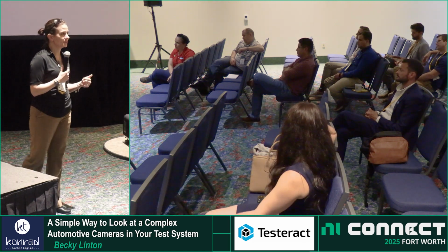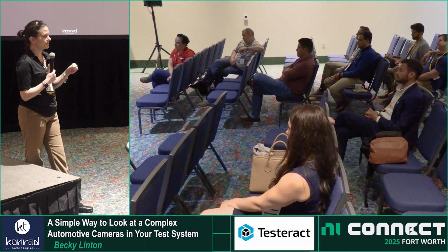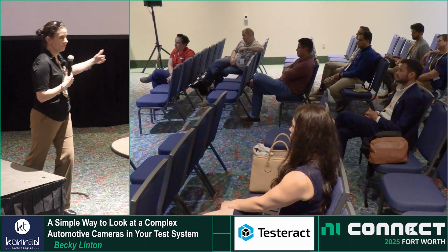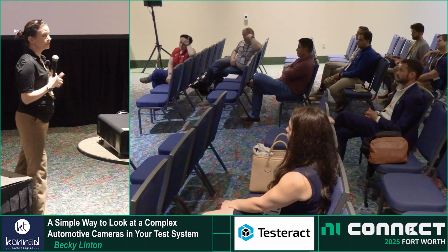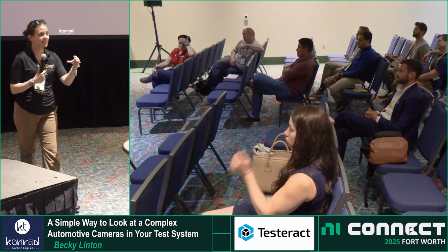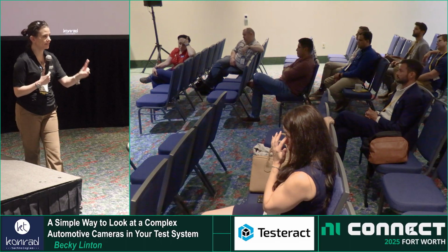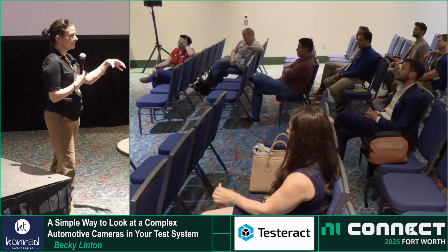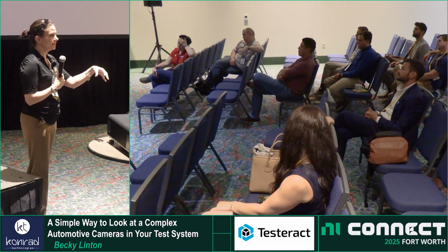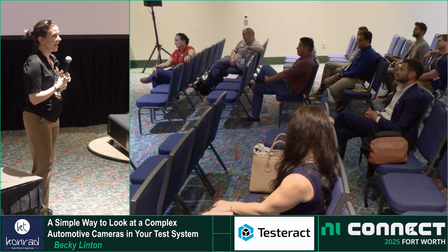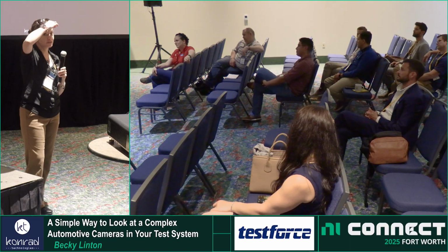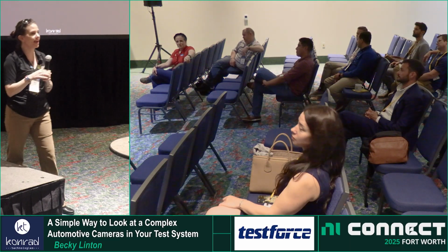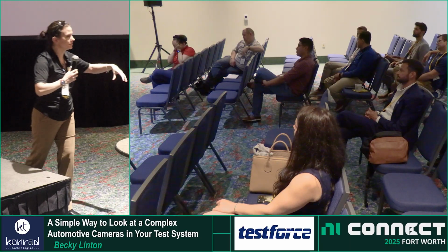Previously, I'm going to explain what their solution was. They literally would have, let's say, 24 cameras with an RF switch. The RF switch would go to a single box that had a deserializer in it. It would deserialize the data and build an HDMI stream. Then they had a camera capture card in a PCI computer. So they were switching between 24 cameras to this single mystery box.